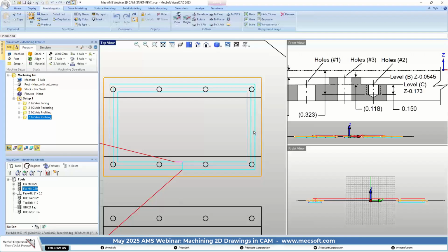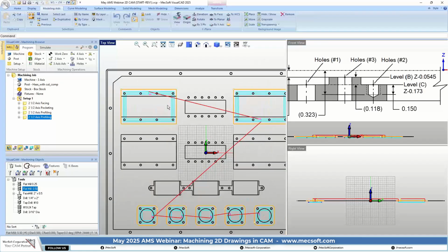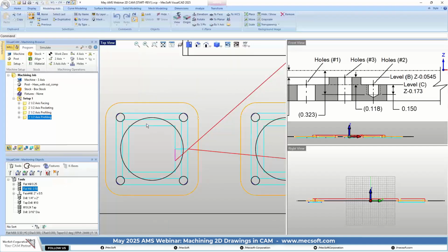I'm not going to worry about that. The way we did it right here is the fastest and the easiest way to understand how to do it. If that concerns you, you can go in and just create like a square box around that area if you want to do it that way on both sides. It's up to you. But we're just doing this perimeter on the outside. And it's the same over here, and it's the same here. The offset, X and Y offset, is enough to clear it past these circles.